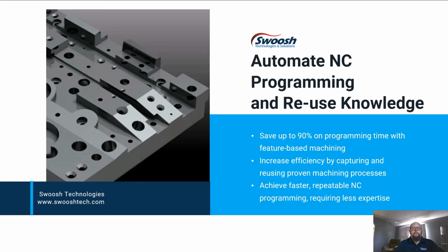Well, feature-based machining is going to cut through all of that, and essentially you build processes based upon individual features. Now you can have a variety of methods for an individual feature. Thinking about, do we want to look at PMI information, and if a tolerance is tighter than some determined value, then we use a different process, more of a finishing process versus just a generic general purpose process.